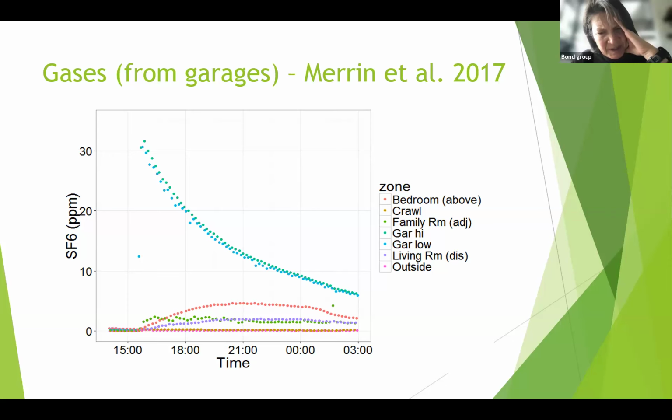That's a really long decay in that house. Did you have an estimate of an air change rate of the house? We do. I'm thinking back to the houses that we tested, and they would have been probably, in terms of natural, in the range of 0.3 to 0.5 air changes per hour.